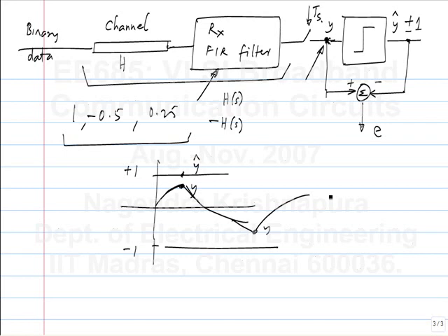And accordingly, we can tweak the coefficients based on the error spectrum's frequency. If we get a lower frequency component, we can go and tweak the first tap. You will detect the spectrum of the error. That itself is a difficult thing. How do you do that? Put a spectrum analyzer inside the receiver. Huh?